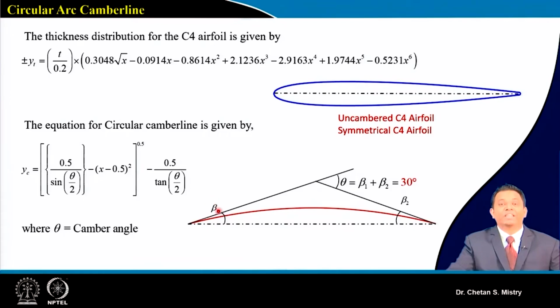These angles, beta 1 and beta 2, are nothing but my metal angles. When I say metal angles, do not forget, we have discussed that our flow angle plus or minus incidence angle, and our flow angle and deviation angle, give us my entry angle and outlet angle, which we have defined as our metal angles. So these are my metal angles.